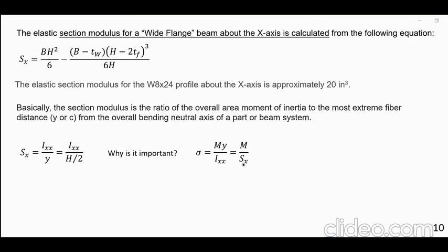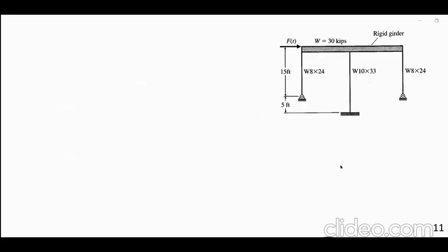Okay? So if you know the section modulus about x, you give me the moment about the x-axis, I can give you the stress. Okay? So there we are. That is why section modulus is going to be useful. Now, mechanicals probably look at it like this mostly, civils look at it like that, and I told you that Sx contains the information about Ix in an indirect way. Okay, so let's go ahead and do the calculations here.